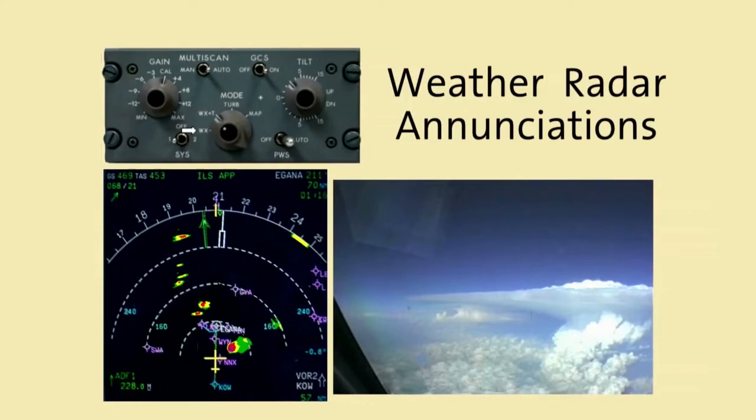In these pictures, note the absence of ground clutter and the thunderstorm cells at 60, 130, and 180 nautical miles. In addition, the radar displays a fourth cell that is over the horizon. The yellow arc is a pack alert function and warns crews that the cell at 60 nautical miles is attenuating the radar beam, and the area behind the cell is not visible to the radar. Pack alert is only active during auto operation when cal gain is selected.